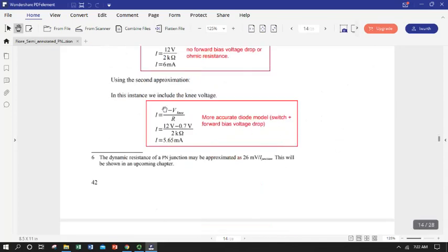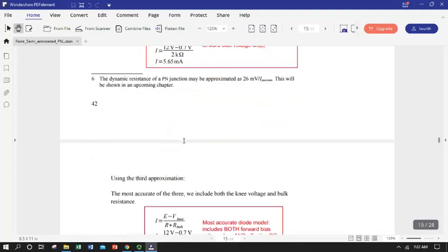So we can express that Kirchhoff's voltage law in this little equation. Mr. Fiore has kind of rearranged terms, but basically the voltage that we have left to apply over the resistor is the source minus that forward bias to get over the hill in the diode. So we'll have a little bit less current available to flow because the diode has got that opposing voltage.